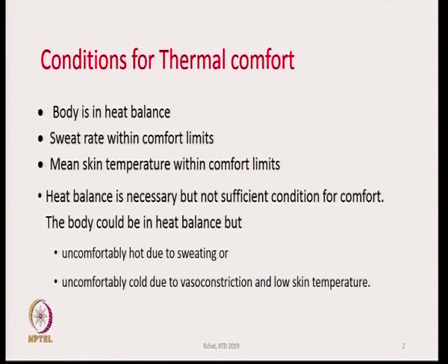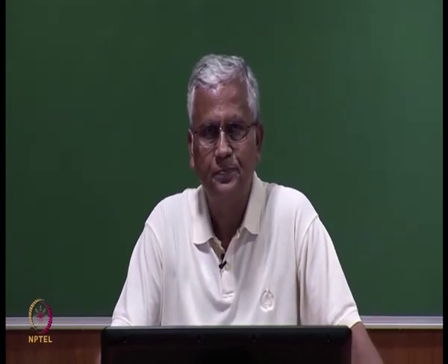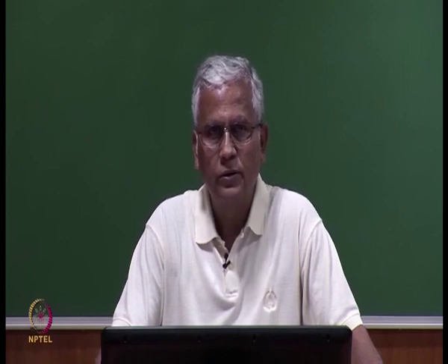Heat balance is necessary, but not a sufficient condition for comfort. This is a very important statement: balance is definitely necessary, but not sufficient for comfort. The body could be in heat balance, but uncomfortably hot due to sweating. So, if too much sweat is generated, we will not feel comfortable, or it could be uncomfortably cold due to vasoconstriction and low skin temperature.